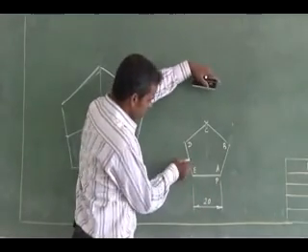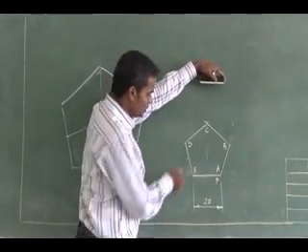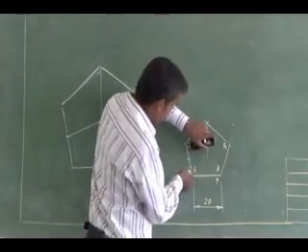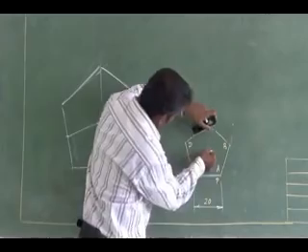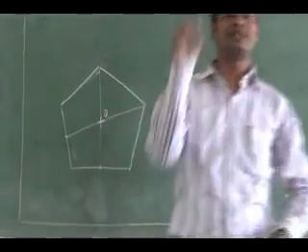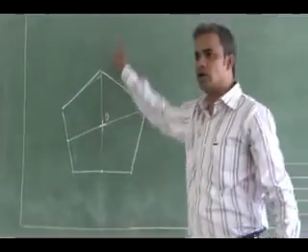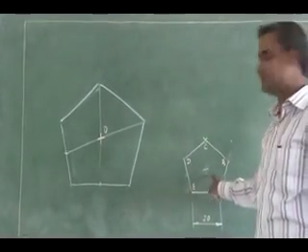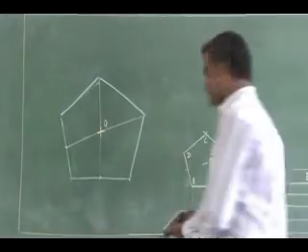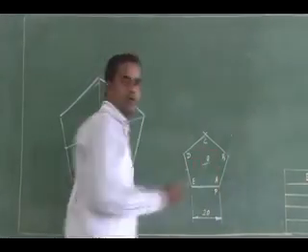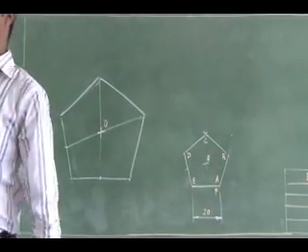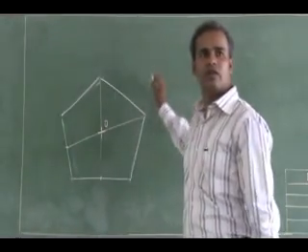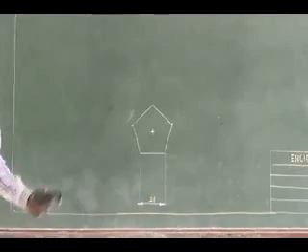Similarly, from the other side, mark the middle, then fix your drafter to the opposite corner, align your drafter, then draw a line so that you get the center. You need not draw all the way, you need not show the bisecting lines. You just get the center like this. It is very much essential. Always mark the center quickly. For pentagons you should not forget to mark the center.